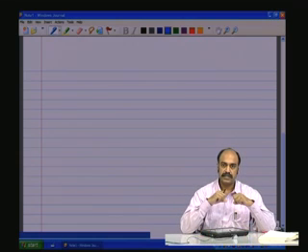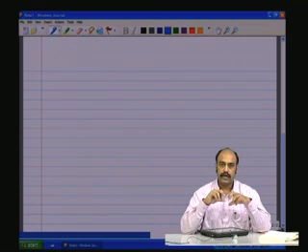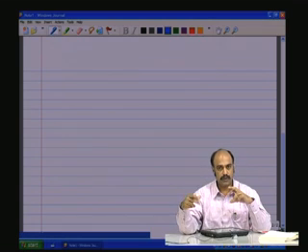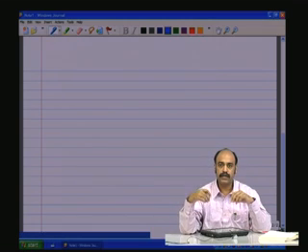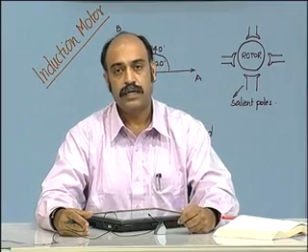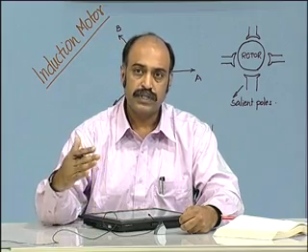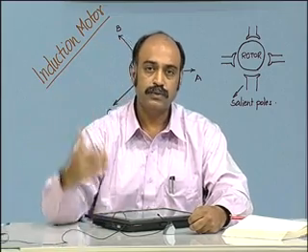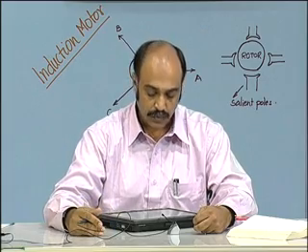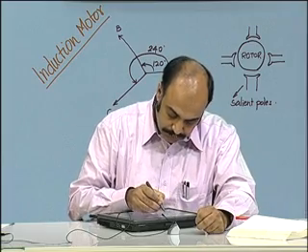The input power is a mechanical power which is driving the shaft of the induction motor, and the shaft is connected of course to the rotor, and the rotor is rotating in the magnetic field, and that is going to induce the voltages on the stator side, which is connected to the load or to an AC source, thereby putting the active power into the source. So the way the energy flows would be in this fashion.